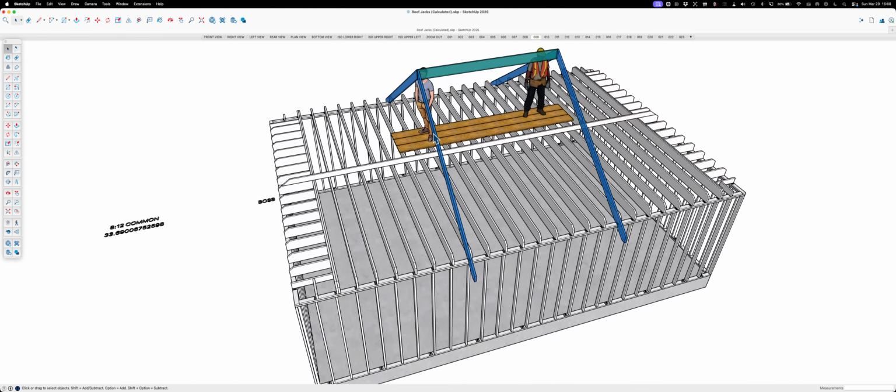I found a couple guys, because at this point here, this is where you're going to need a couple guys. I've done this with 2 people. Like, I'd be down here with the gun, and then I would run up here, and this guy here would have this rafter on his shoulder, and then I would go down here and he would raise this one up, and I'd have them put the 2 of them together with about 1.5 inches space, just whatever, so that I could shoot.